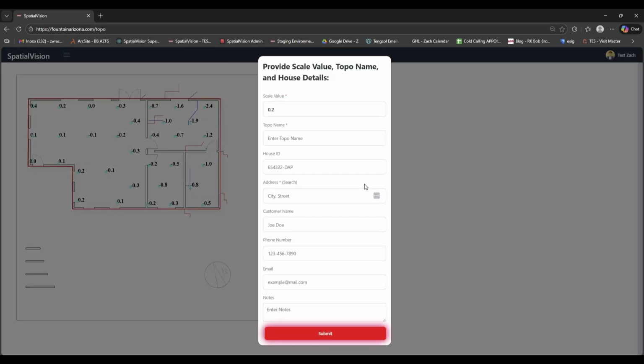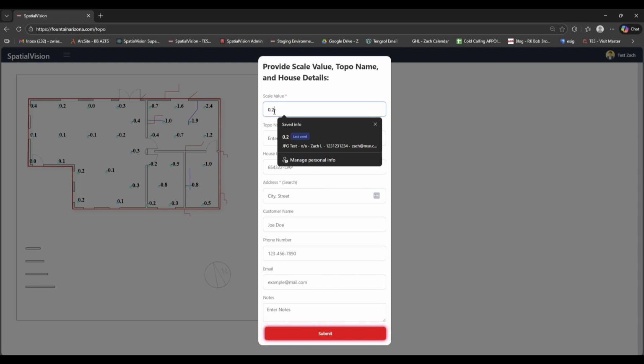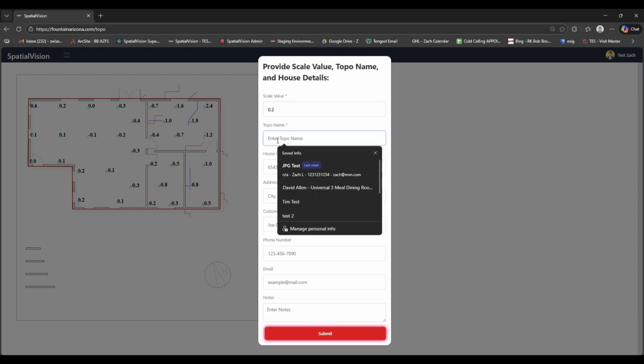All right, this is our last page before we start to see maps. Scale value. This is your color contour interval. Every time you see a color change on that map, it's going to indicate 0.2 of an inch of movement up or down. You can change this if you have a lot of movement across a home. We feel this is a pretty good scale for 95% of the homes you're going to read residentially or commercially.